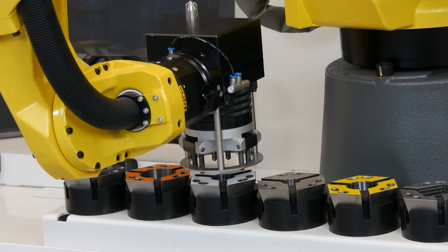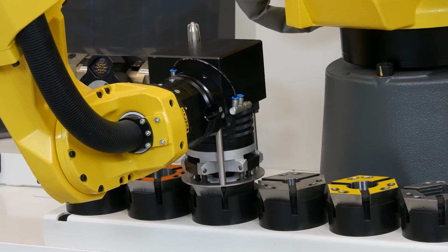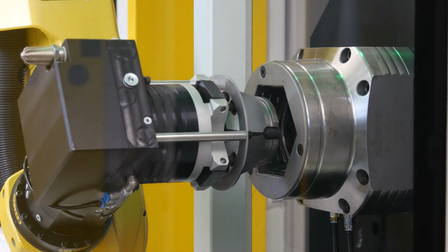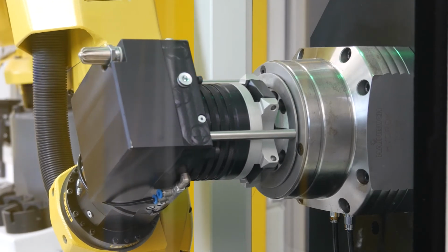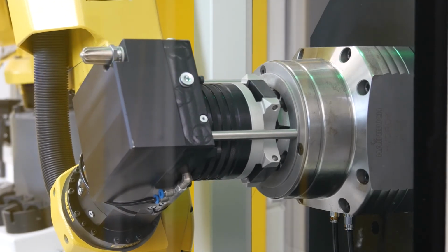We'd like to share the technology we use and also developments we see in the industry to use your machine more effectively. One of these functionalities is collet exchange. Automatically exchange collets in your lathe. The robot will pick a collet, place this in your machine clamp, then go to pick a product from the tray and place this inside of the collet.